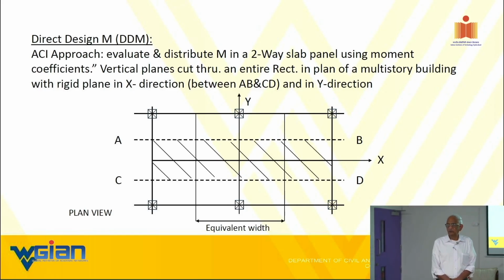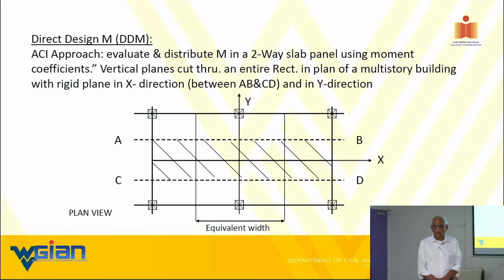That's how we're going to assume, rightly or wrongly. But this leads eventually to a crack. At failure, we are not talking about it at the service level, at failure, you're going to have a crack. And obviously, that crack initiates at the geometric center of that slab. Then it will start to extend.